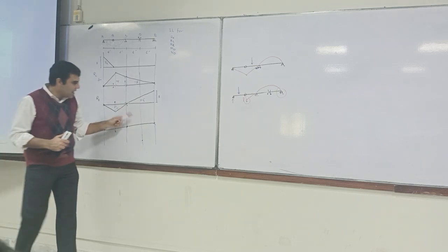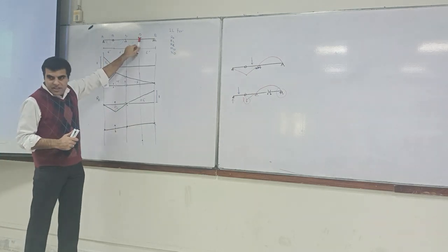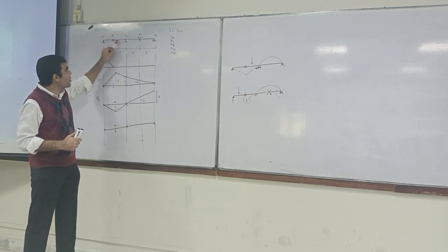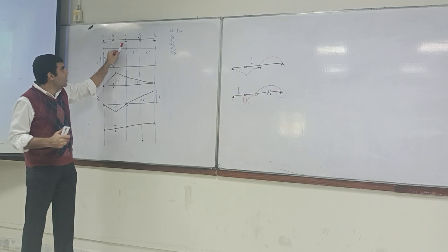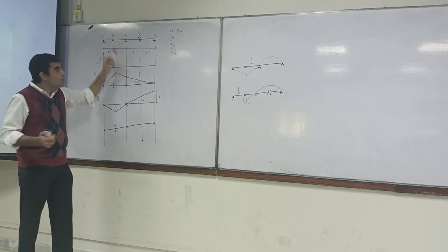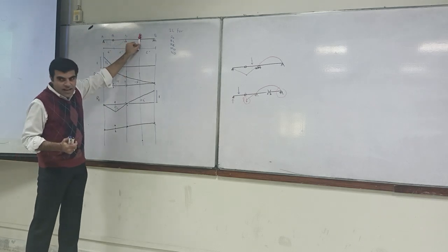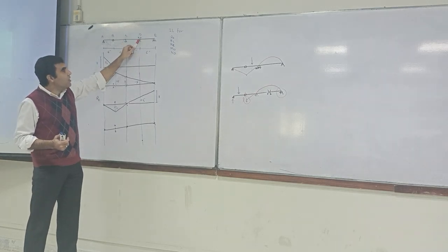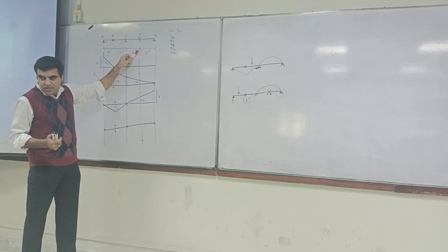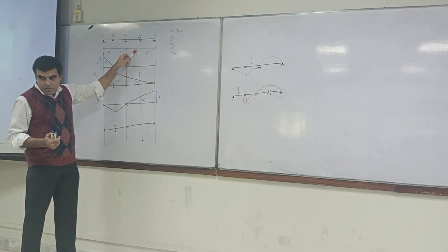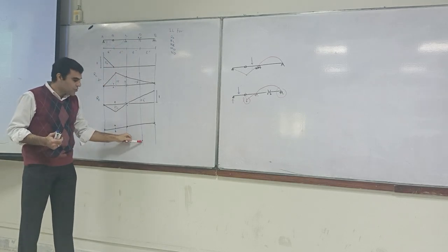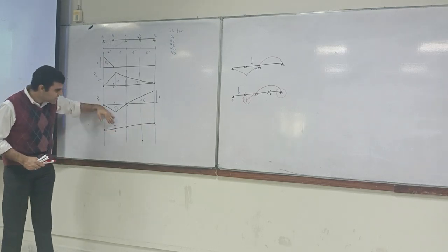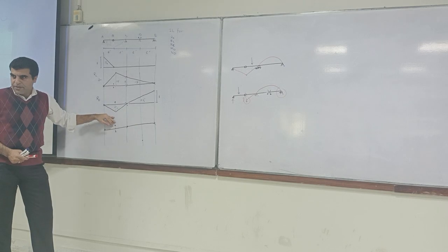And when you come within this span, then this is just a simply supported beam. The other parts are doing nothing. All the rest of the member becomes redundant. So when you move it inside, the tension is at the bottom fiber. That means we should have it over here. If we do it over here, this thing will automatically be adjusted.